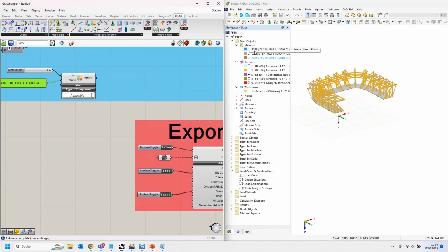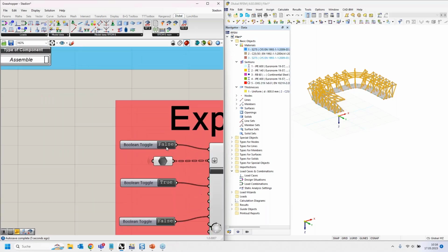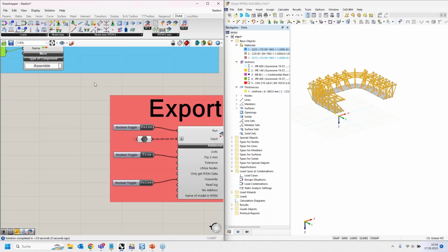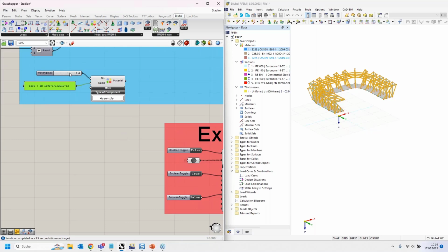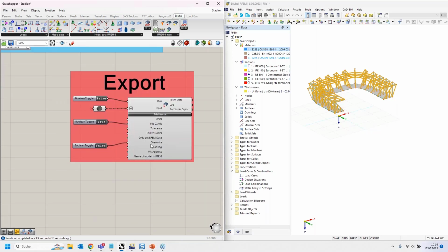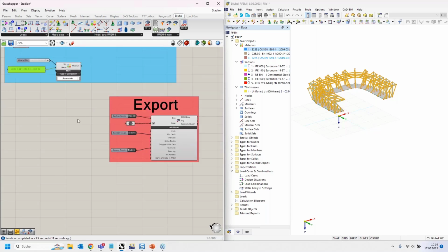So let's do it again, 235, let's say, just to see it. So I want to change this from S275 to 235. I run it again, and you can see the change. All right. So you can also modify objects if you assign the index number to the object, use this add functionality, and then modify the structure.